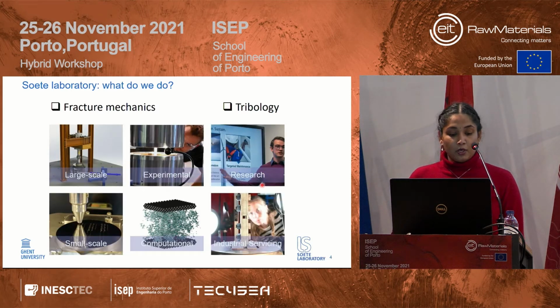We do small-scale testing, as shown in these figures, where the sample size can range from 4 millimeters in length and 5 millimeters in thickness, with loads of 0.5 to 1 newtons, to large-scale test rigs, where we have bearings of 400 mm in diameter, which are the real-scale bearings used in water gates in Belgium to close and open whenever there is flooding or water levels rise. These large-scale test rigs have a load range of 1,500 kilonewtons, and those are the scales of loads we work in.